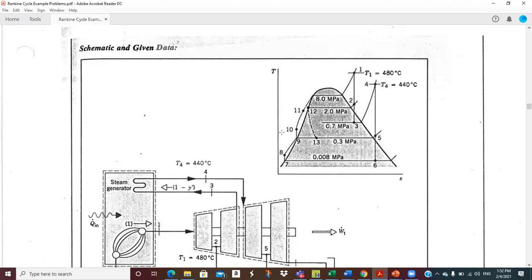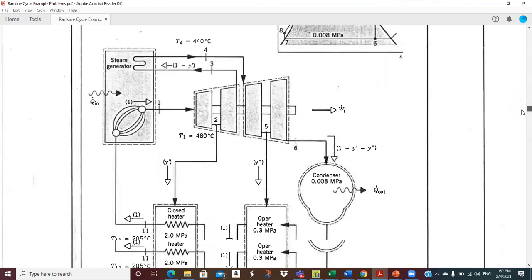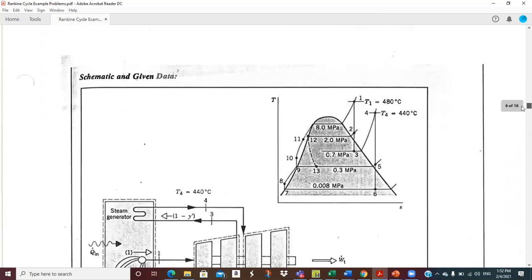But, gosh, where are we? I guess state 11 is probably going into the boiler? Yeah, we're going into the boiler at 11. So main steam, feed water at 11 to 1, partial expansion to 2, that'd be an extraction point.